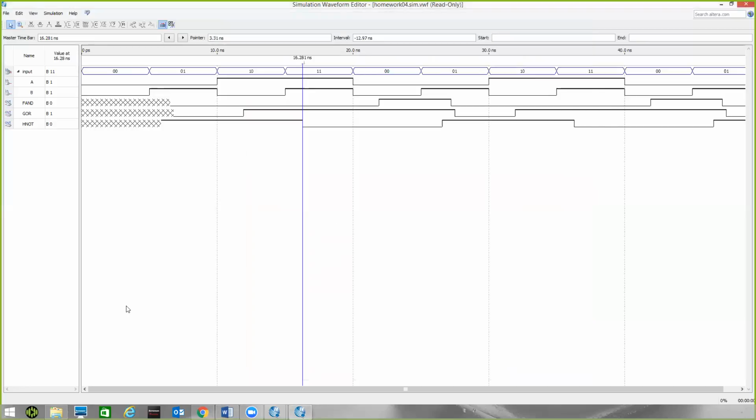Now let's look at the rising edge delay for this NOT gate. So we can see that the output transitions back from a 0 to 1, the edge rises from low to high right here. So we look for where the input transitions from high to low. Well, it transitions here at 20 nanoseconds. A goes from 1 to 0, high to low here.